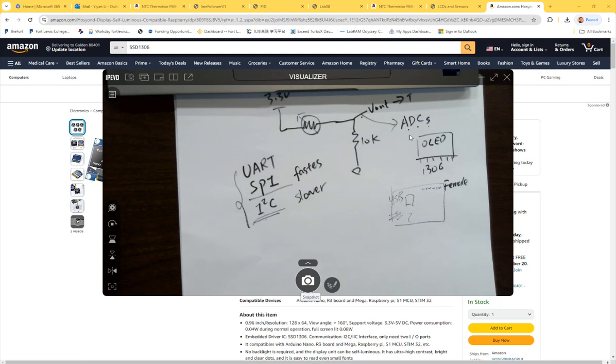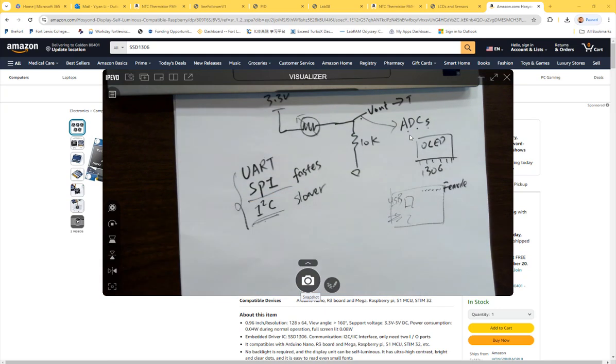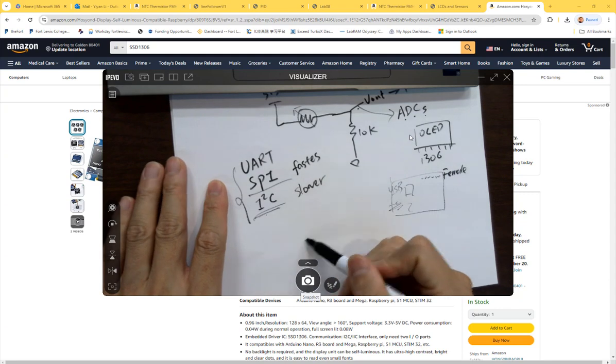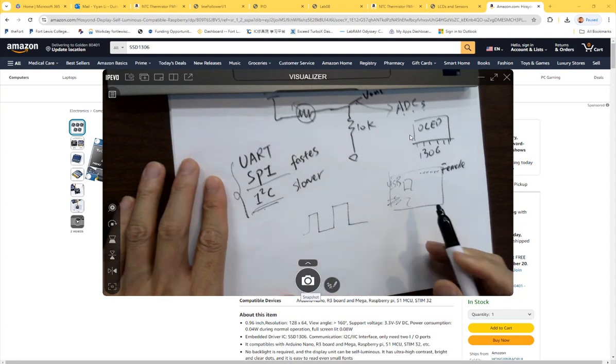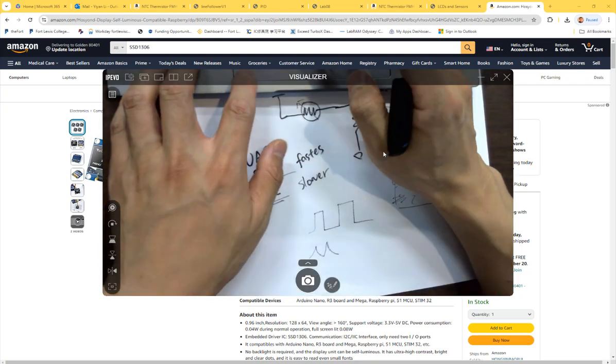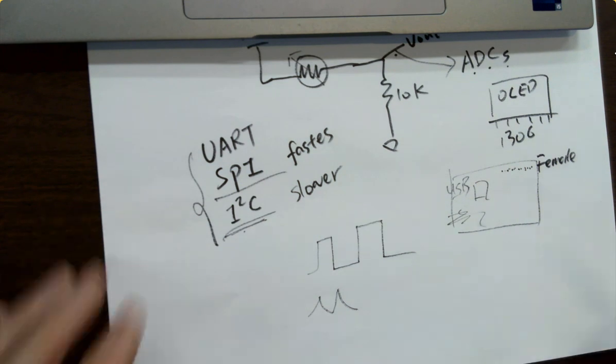They have time delays. So if you use SPI to transmit over 100 meters, you won't be able to get good data. Instead of getting the full digital value, it's going to oscillate, not charging up yet and then starting to discharge. You know what I mean? So they have time delays. So for long distance transmission, it could be a very good interview question.